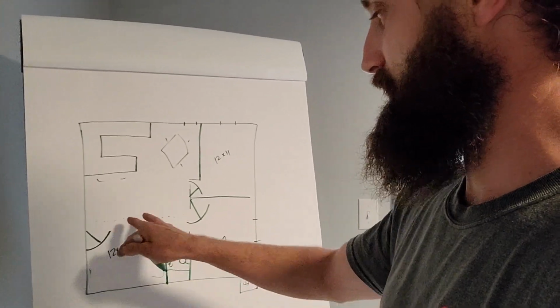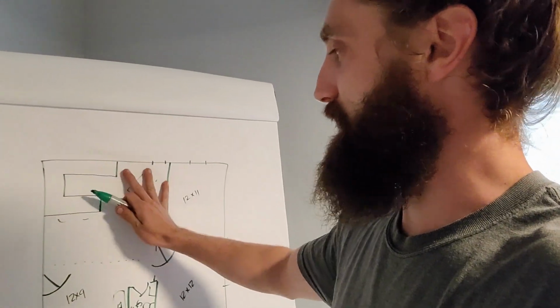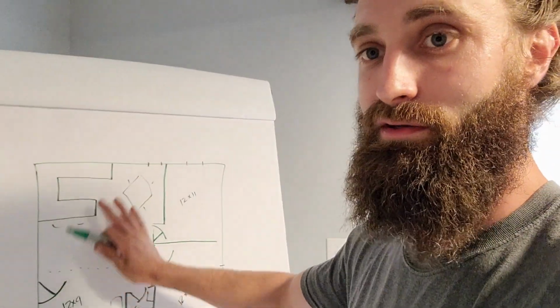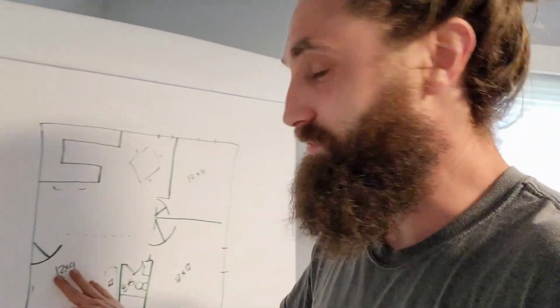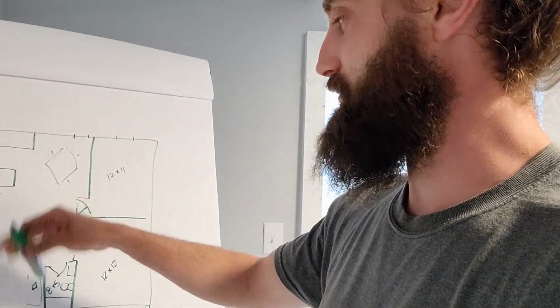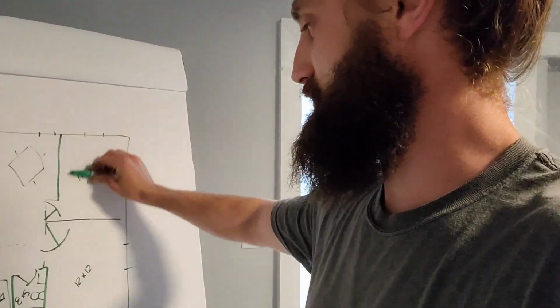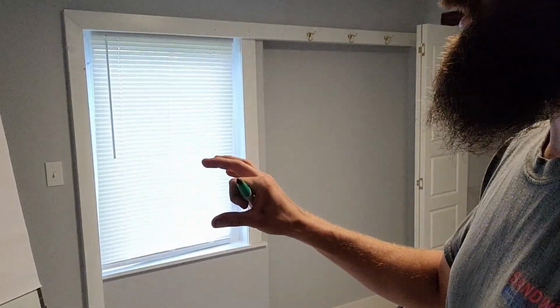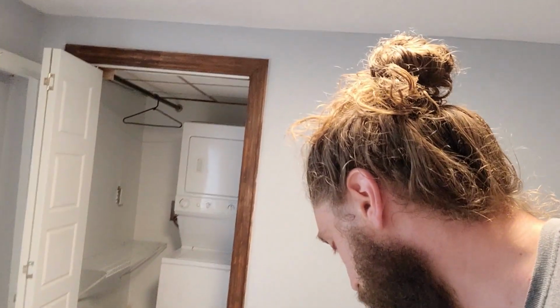I need to look at the living room area as a zone in itself, the kitchen as a zone in itself, because I want to get as much supply to each zone area or wherever our high loads are. That way, we're not feeling a lot of draft to where we're dumping air into one area that doesn't need it and sucking it over towards the kitchen or towards wherever our returns may lie. And so I will kind of chop things up a little bit.